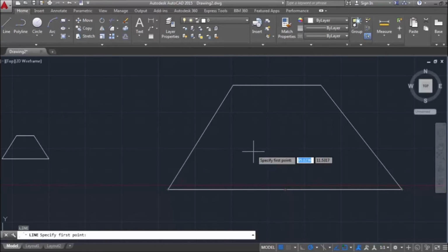By default, a marker is this green triangle and this rectangle that's showing up on a line when we're hovering over it. So a marker and a tooltip are displayed when you move a cursor over an object snap location. This is called AutoSnap. It provides a visual confirmation that indicates which object snap is in effect.